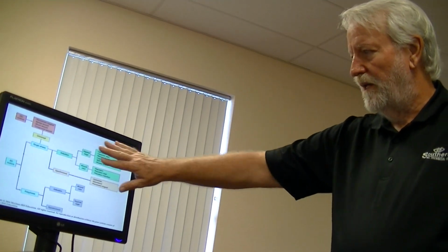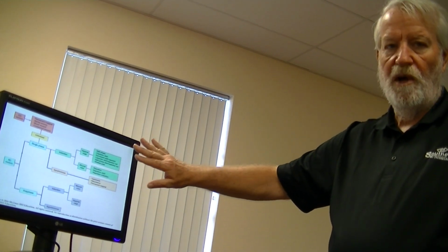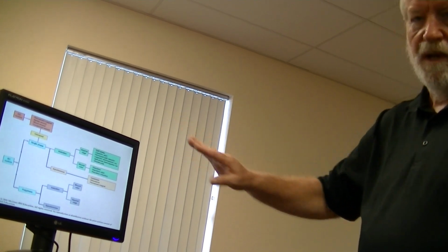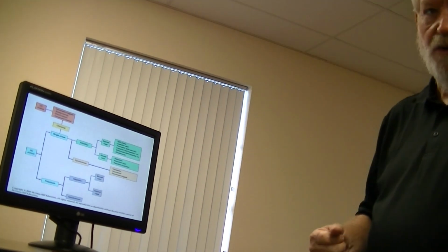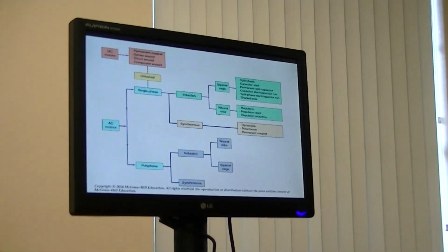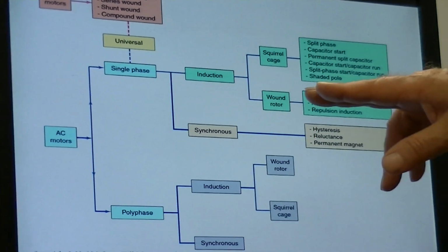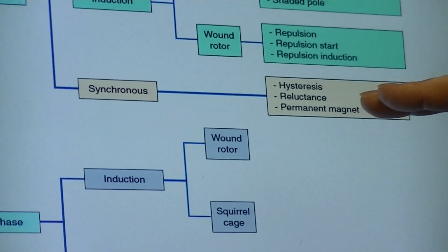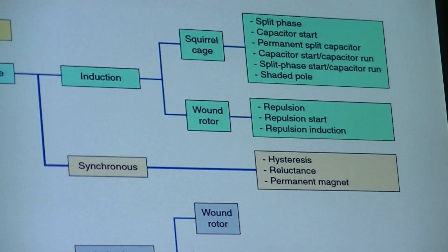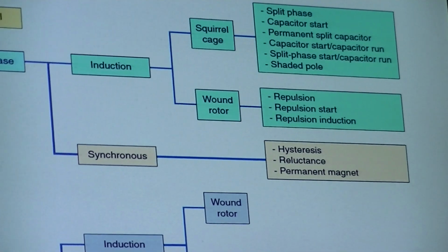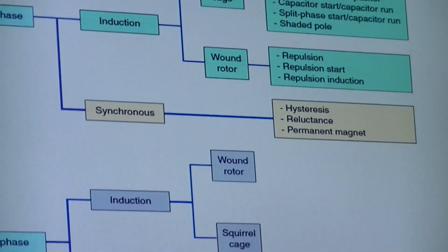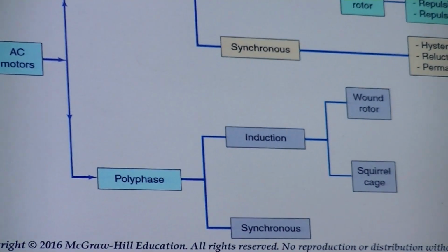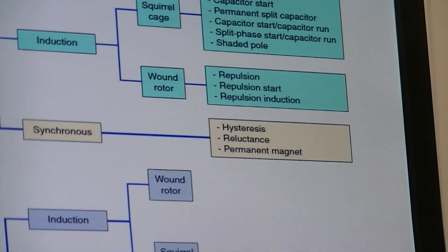All right, now, again, that's single phase. They're usually small horsepower motors. I don't think you'll ever see one over about 5 horsepower. A lot of times they're fractional horsepower, like 1/3 horse or half horse or 1/10 of a horse or whatever. And then the synchronous, you've got permanent magnets, but you have the capability of basically, believe it or not, controlling power factor. Because if you under-excite, okay, you're giving excitation to the coils, and if it has a synchronous speed.